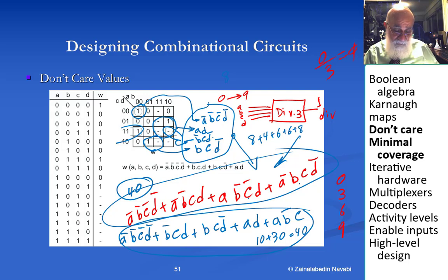So that becomes 12, 20, 28, 30. 2 gates for this realization. Therefore, using don't cares as don't cares, and sometimes taking them as zeros, sometimes taking them as ones, is the most appropriate way of treating them, so that I can reduce the number of transistors in my circuit.